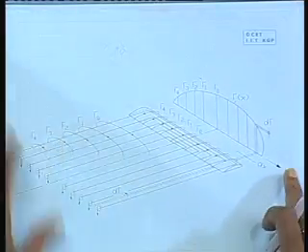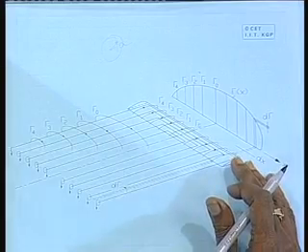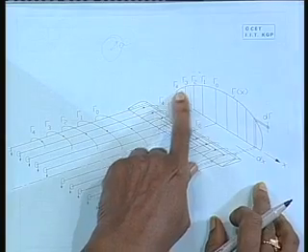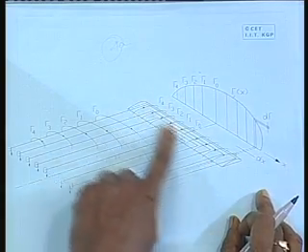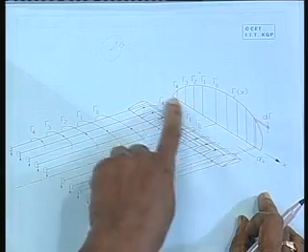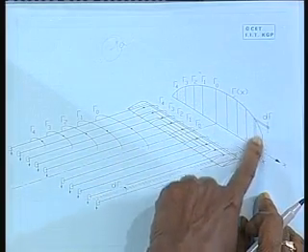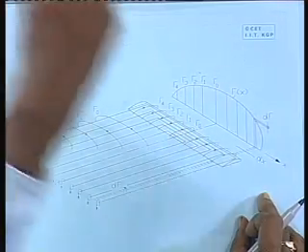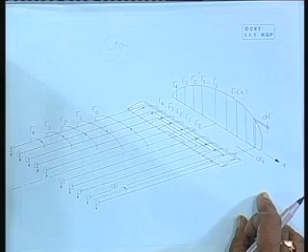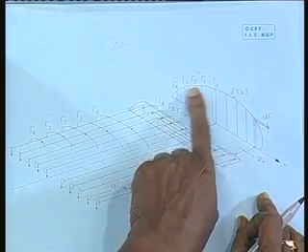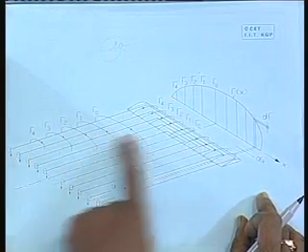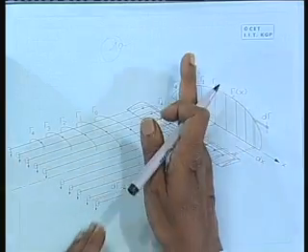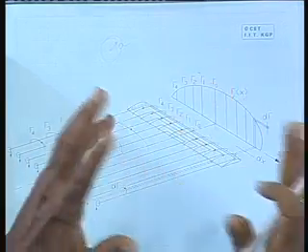If we extend it to the propeller, because of the blade section changing, the circulation on the span of the propeller blade changes from 0 at the ends to a maximum at the middle. It is not a constant strength of circulation. Circulation changes from one end to the other, and you have these trailing vortices shed because of the change in circulation strength. Artificial endings are created because of the change in circulation.